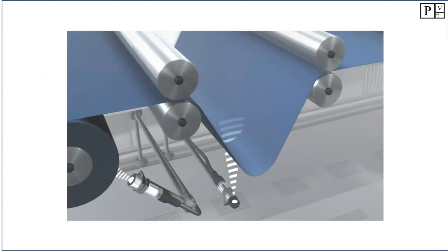Okay, next one. We're looking at different fabrics, or we're looking at a paper mill. The paper is having a dip here to reduce the tension on the line there. So again, we could use a diffuse sensor to look at this. We could also use an ultrasonic sensor. It looks like we are looking at an ultrasonic sound wave being depicted here. So let's go with the ultrasonic sensor.